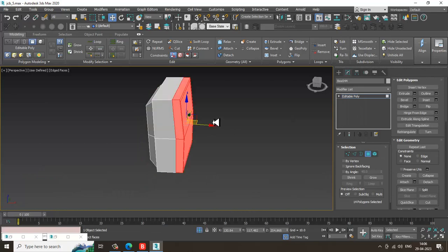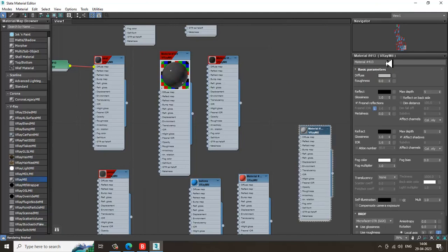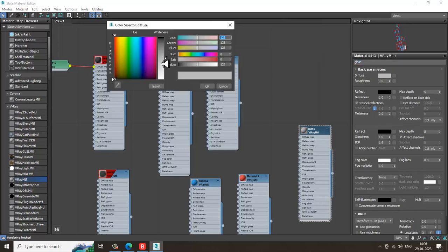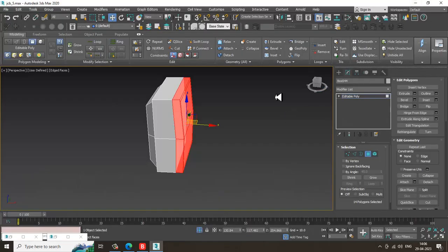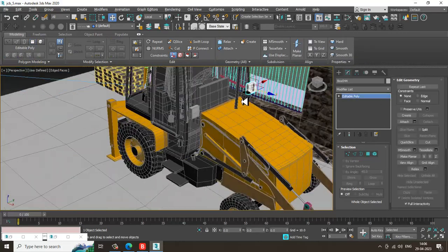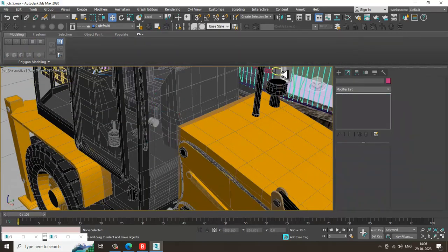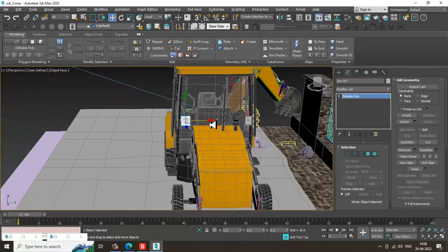Control I, inverse, and let's go into Vray material. Let's just give it a bit of a glass. So I'll slightly give a color, I'll give a refract, give a bit of white, and assign it. That's it. So I'll just end isolate this, and if required to give a frosted glass, you can make it a frosted glass by adding a noise in the bump map. So that can be done in this way.